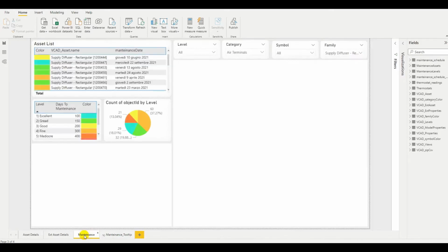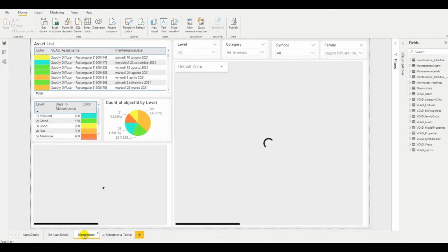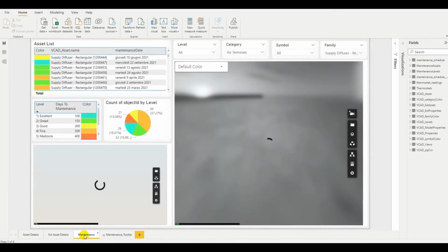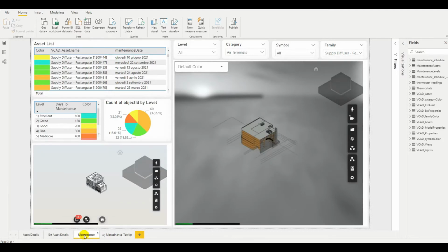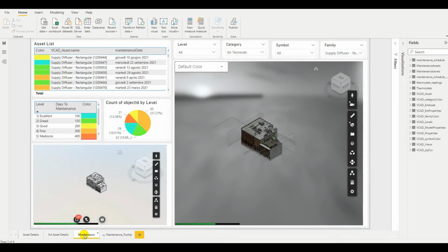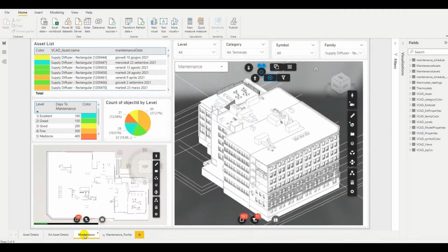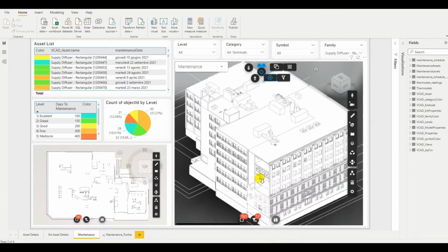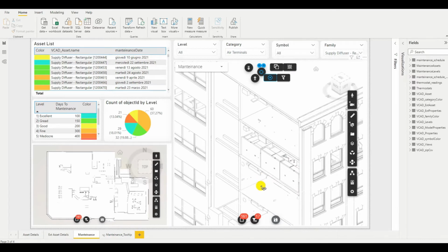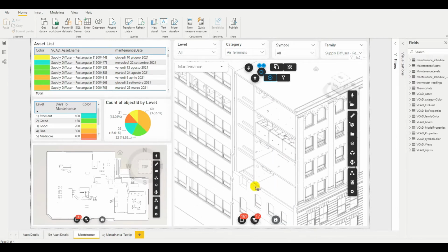This comes in very useful when you have some geometries which are hiding the view for the geometries that you actually want to focus on in your report. So think about hiding stuff like walls or ceilings and floors, for example. Again, now the scene has already been set up with the Forge options. The camera snaps to its original position, and the hidden objects remain hidden, so we can see through that wall that we hid.